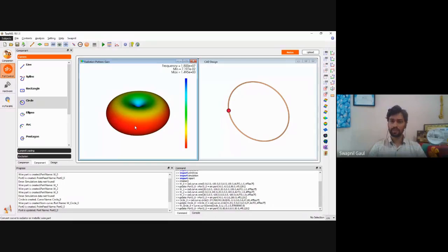Right now we don't have a lot of time to discuss those examples, but I have also simulated the combination of this loop antenna and dipole antenna. Then we plotted the near field, and we saw how it propagates in a circular fashion. So we have observed that circular polarization also. And in the same way, in the folded dipole antenna, we have seen that to increase the impedance, the n square Z0 formula. Even in the case of array antennas we have seen that if we have more elements, we are going to increase the directivity.